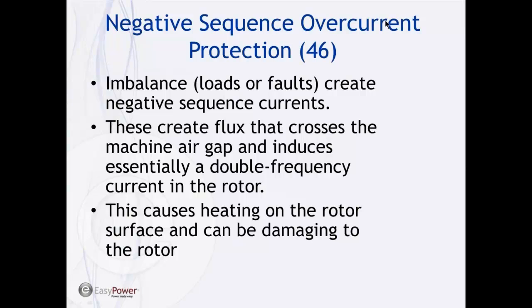So anytime we have imbalanced voltages, imbalanced loads, we have negative sequence currents. If you're familiar with symmetrical component theory, there will be negative sequence currents for any imbalance, whether it's a load or a fault. The worst case scenario we're dealing with would be a phase-to-phase fault in the machine. And that's going to generate huge value of negative sequence current. Now, negative sequence currents are basically in a reverse phase rotation, phase sequence from the normal power system.